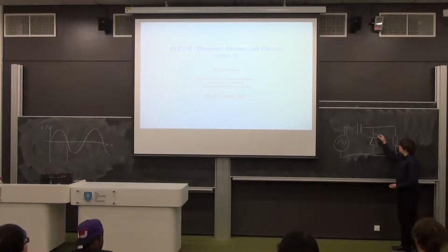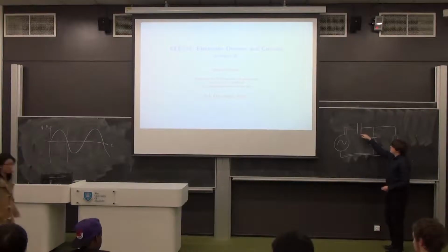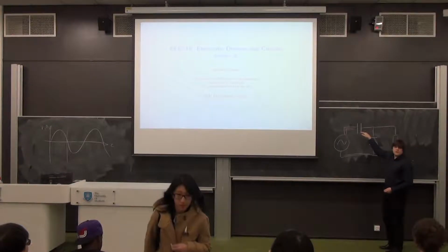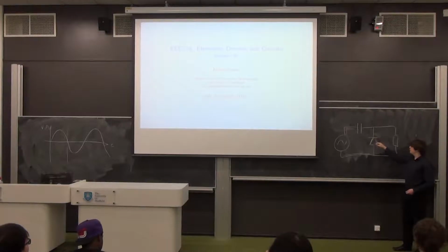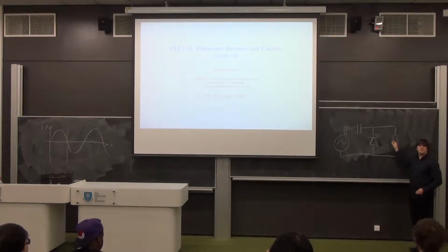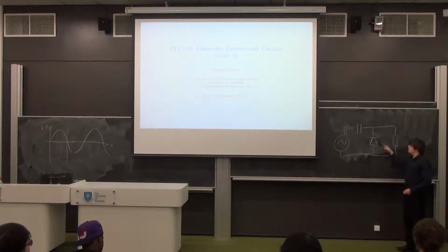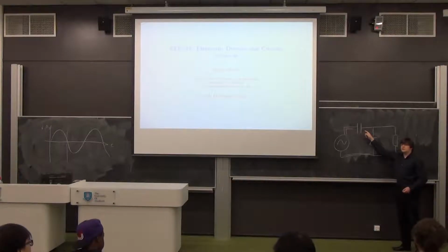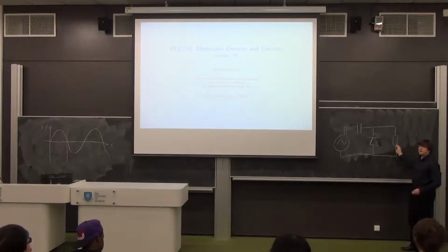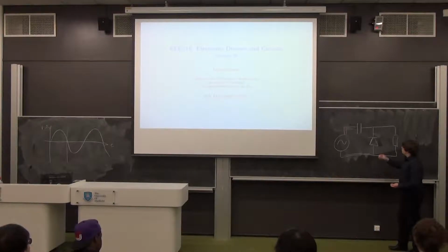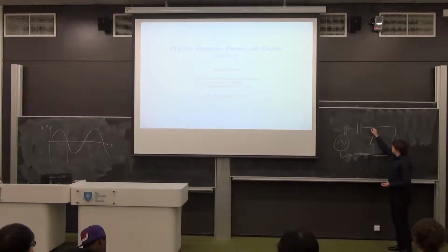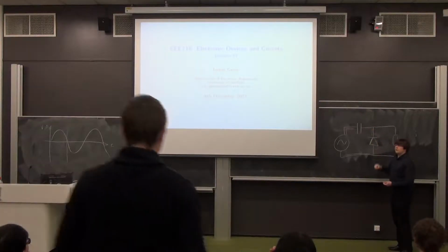So I'm going to assume that since the capacitor can't charge quickly at the moment, because the diode's off and the resistor's large, there is no significant amount of charge able to pass into this capacitor, because this resistor stops it in the period of time that we're interested in. So this node becomes high voltage as well.